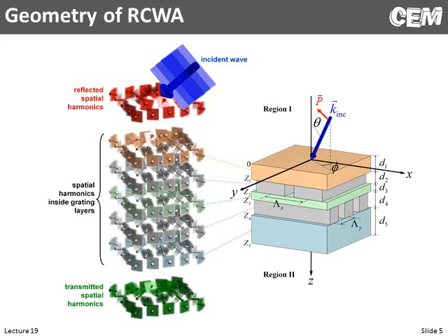So if we have a curved device, what we'll need to do is divide it up into a whole bunch of layers and then approximate each of those layers being uniform in the z direction, albeit very thin, and that's called the staircase approximation. Now this is a Fourier space method, so in each one of these layers we're going to expand the field into a plane wave basis.